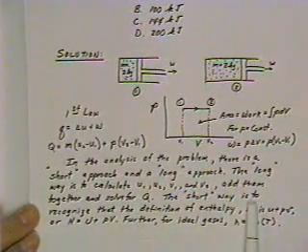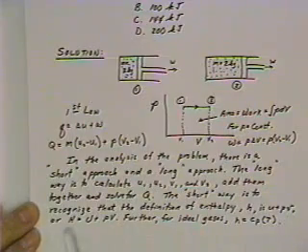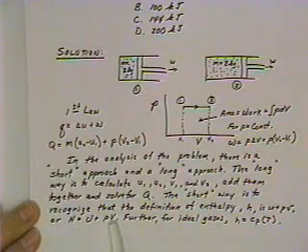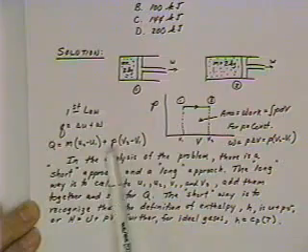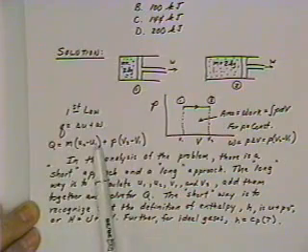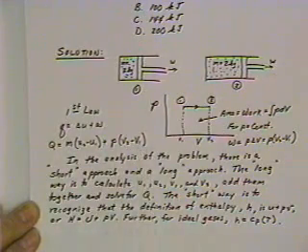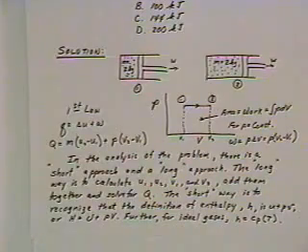So the short way to look at this problem is to recognize that since the enthalpy is defined as U plus PV, or total enthalpy capital H is equal to capital U plus P times V, if we combine the mass times the internal energy term, M U2 plus P V2, that's H2. And M times U1 plus P times V1 is H1. And so this problem boils down to Q is equal to just the mass times the change in enthalpy.